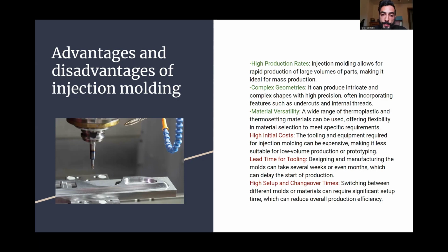On the downside, injection molding has its disadvantages too. Some of those are the high initial cost, which is the equipment required for the injection molding, and the lead time for tooling, which means that the mold could take a lot of time to be produced before starting to produce the parts.